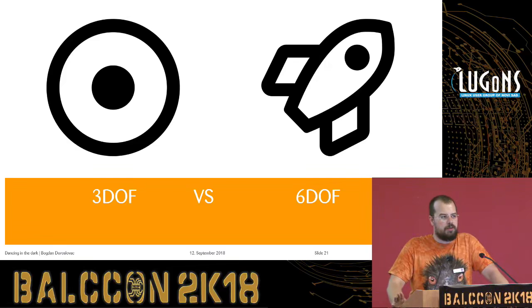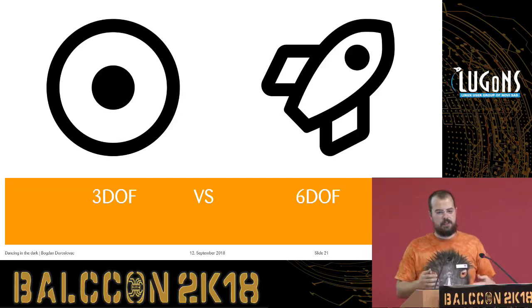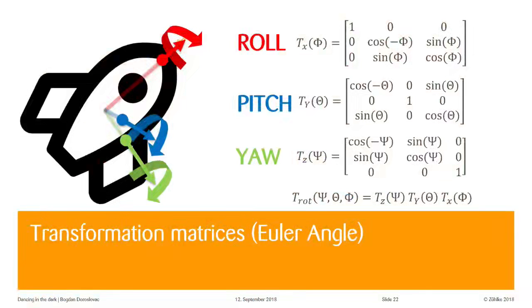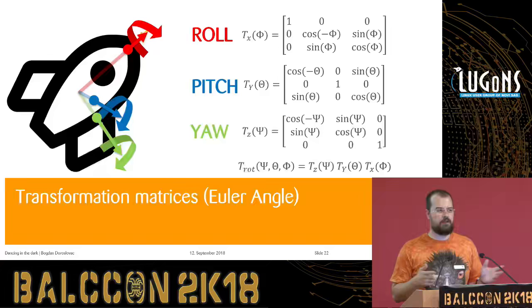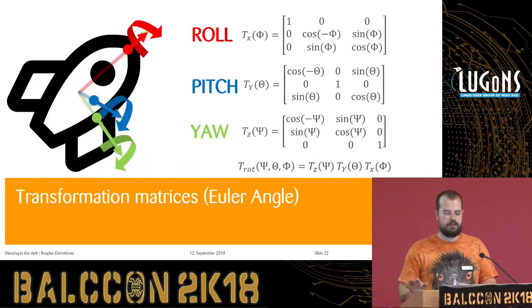The typical approach is to use the strap-down navigation system, which does all the calculations and basically forms a virtual platform analogous to one being in the middle. And it does so by constantly rotating the thing. These are some reference matrices; basically, in order to be able to rotate about an axis you need to use this. Anybody familiar with 3D graphics will notice that it is pretty much the same as what you use to rotate images. And navigation is actually simpler because skewing is not possible for rotation matrices. There is no scaling, there are a lot of these eigenvector cool features. You can forget all that and just use simple rotation and translation.